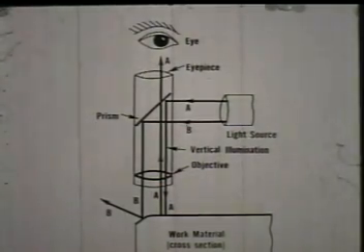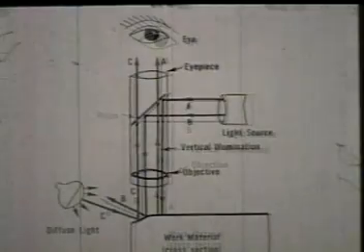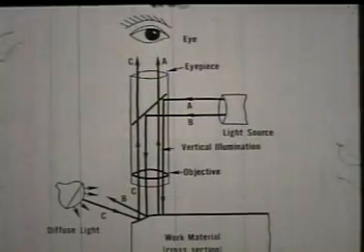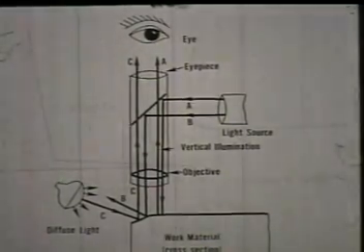If only the microscope light is used, the plastic deformation region and the chip would simply show up as a black, featureless area. However, when supplementary diffuse light of the proper intensity, represented as C, is used, the features of the plastically deformed metal are visible. Due to the absence of the microscope light on these areas, they appear darker.